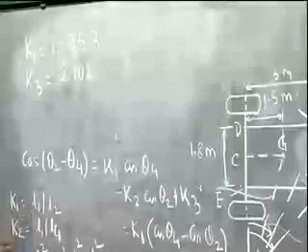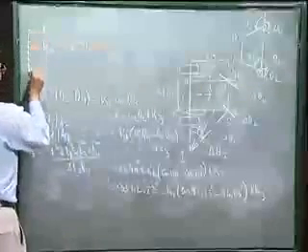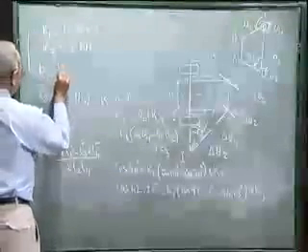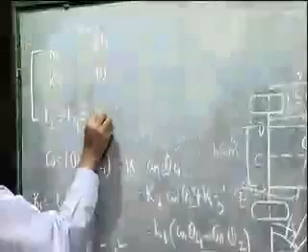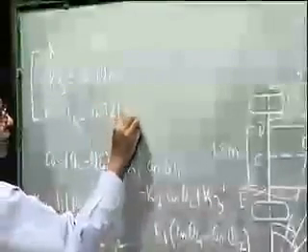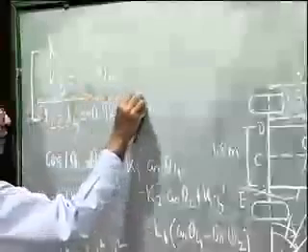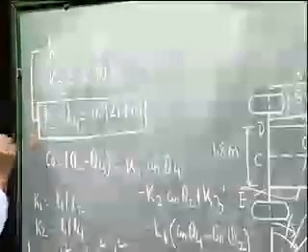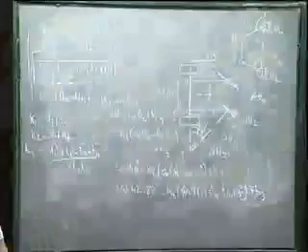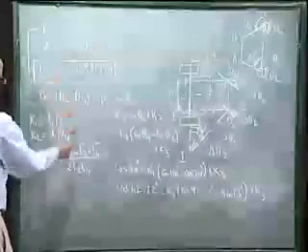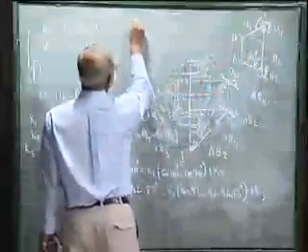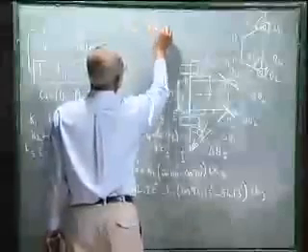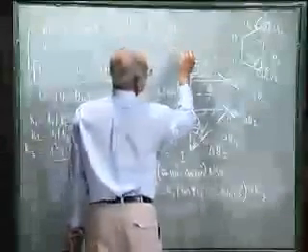So L1 is given to us, L1 is O2O4, which is 1.8 meter. So from here I get L2, which is same as L4, equal to 0.9217 meters. K3 I can use to solve for L3, but I can also use this configuration where I can see that L1 is L3 plus 2 L2